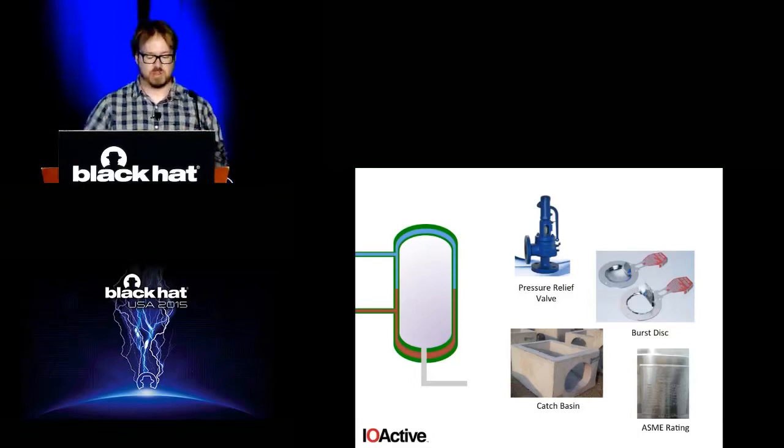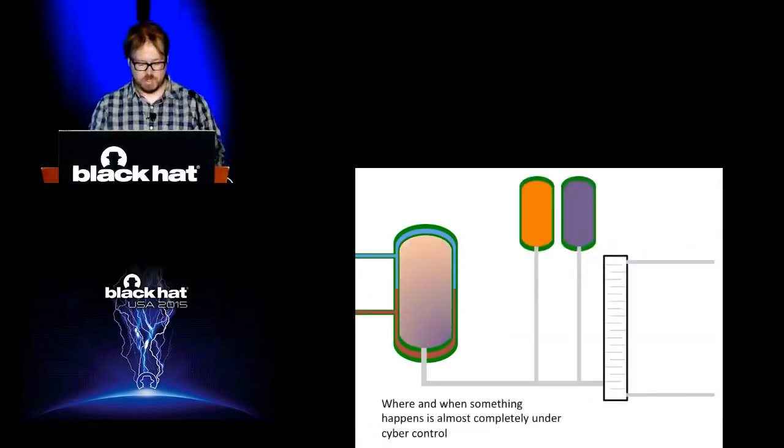They have pressure relief valves in case you overpressure them. They have catch basins sitting below them in case stuff boils over the top and runs out. They have burst discs that will relieve the pressure for sudden pressure spikes, and they have ratings that say we've tested this thing to so much pressure and it took it. So where and when something happens is almost completely under attacker control.